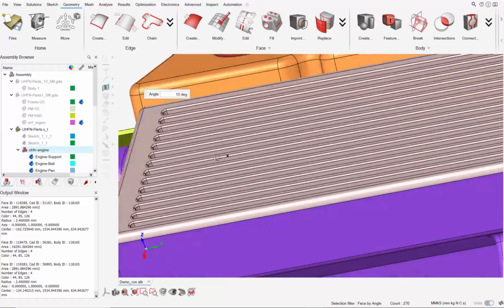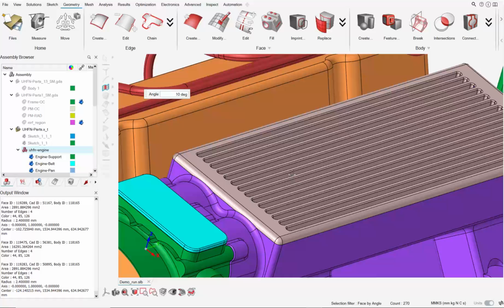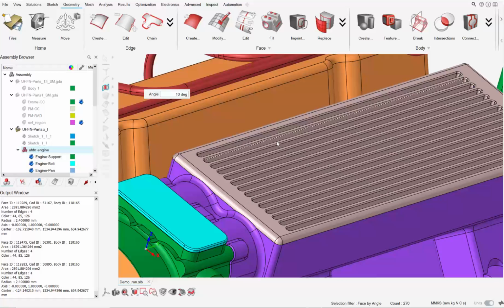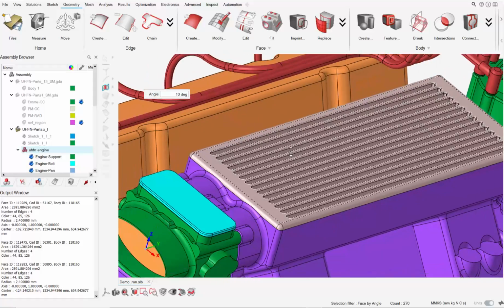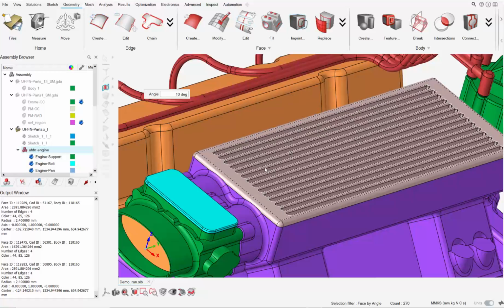Okay, so this is exactly what we want. Because we're going to place boundary conditions on 272 surfaces, in case we don't want to do that again in the wrapping workflow, I will detach it into a separate body. And then I'll place surface mesh control on that detached body.